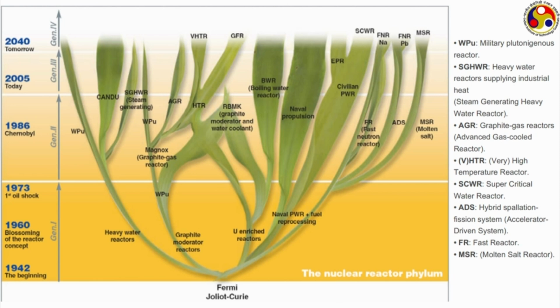The first group of nuclear reactors generally are of 3 types, or I can say 4 types. The uranium enriched reactors, which generally used water as the moderator and the working medium. Then graphite moderator reactors, which are related to the gas cooled reactors, and of course, the heavy water reactors, that is PHW or CANDU reactors. And on this side we may have the thermal reactors.